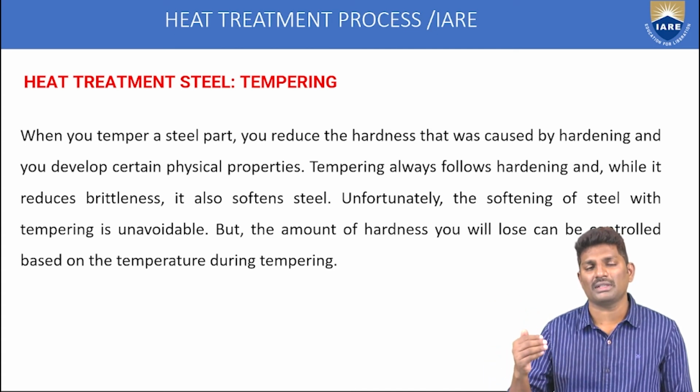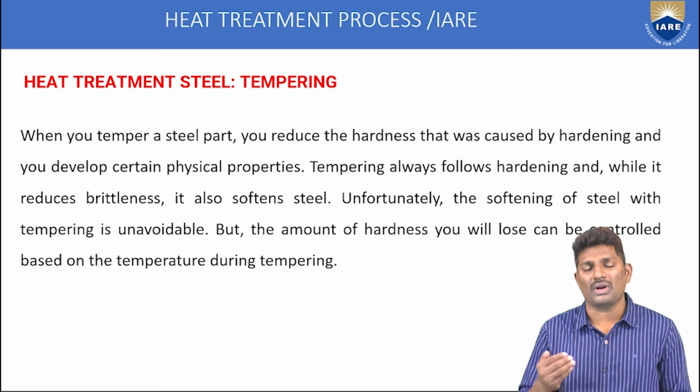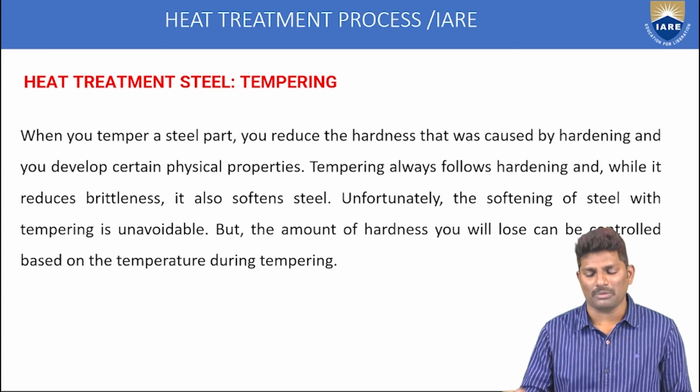The hardness of the material should not come down. So in order to compensate for this hardness of the material, we try to increase the temperature during the tempering process.